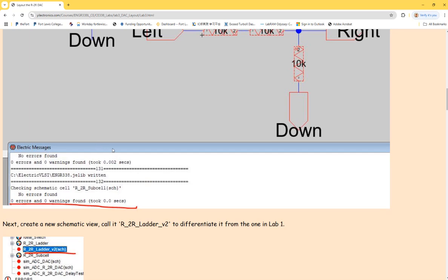Do a DRC check in your report. Every single step, every single sub module, do a DRC check. It's just F5. Don't wait until it's too late. So do a DRC check before moving forward, so you know it works and you can repeatedly use it. And show the DRC check window in your report to receive credits.